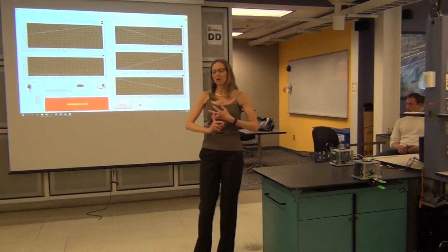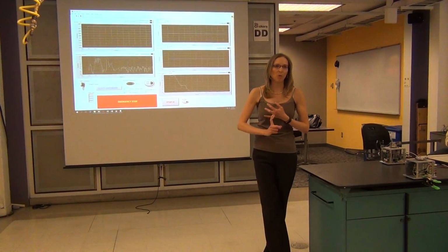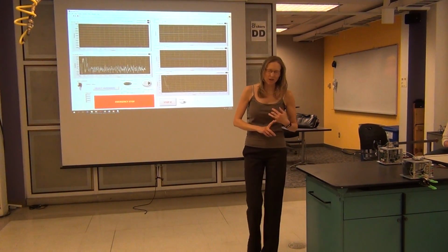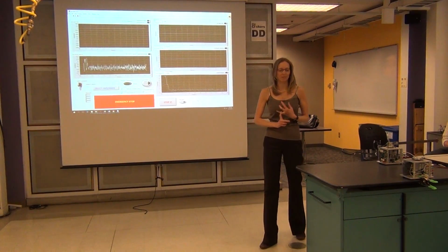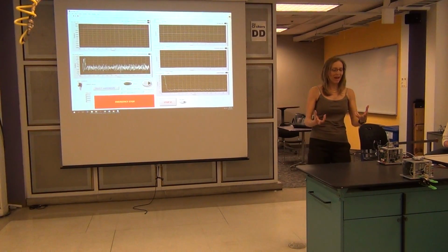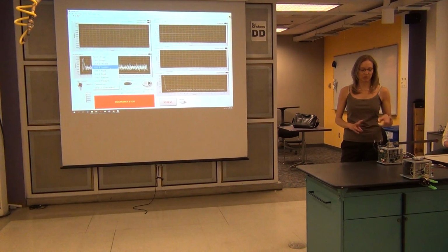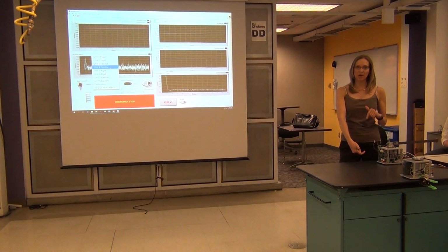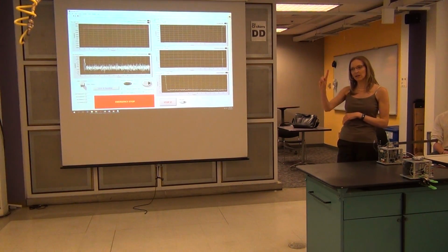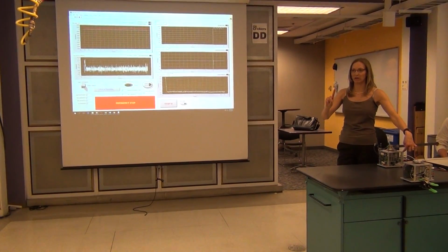So now you have what's called a single output, multiple input system, MISO. So what we have for feedback is 2 sensors, our strain gauge and our potentiometer, but we still only have the single output, which is our DC motor.